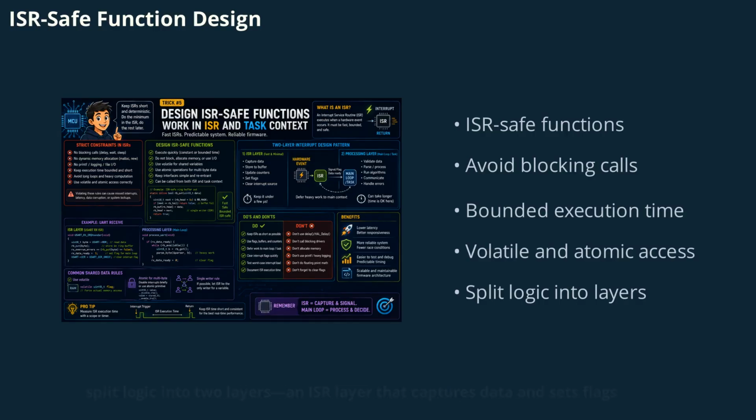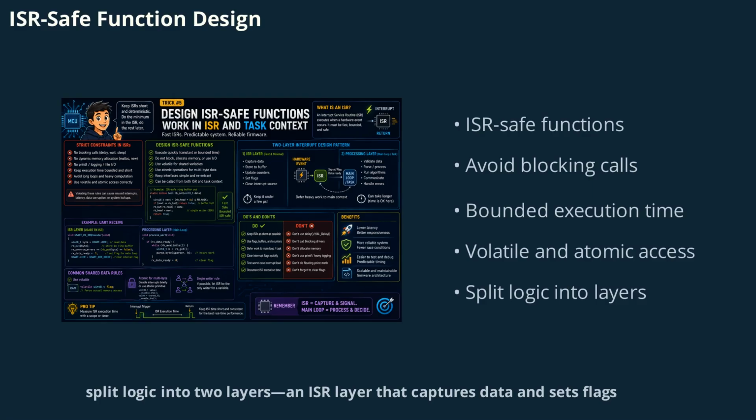Advanced tip: split logic into two layers, an ISR layer that captures data and sets flags, and a processing layer that runs in the main loop. This pattern simplifies interrupt-driven designs and improves reliability.